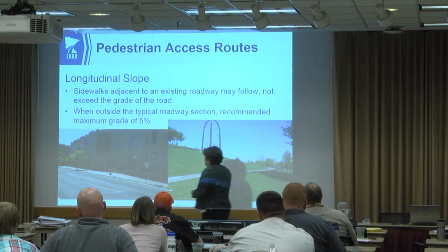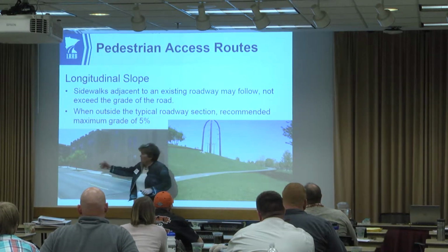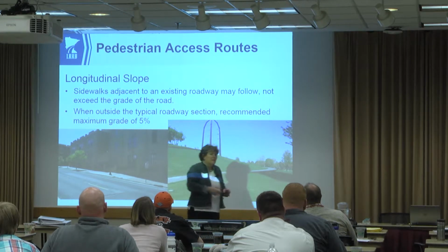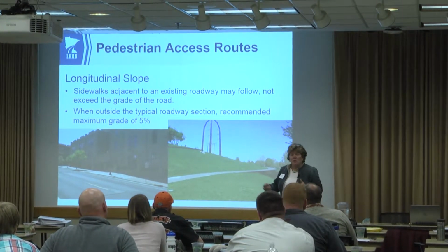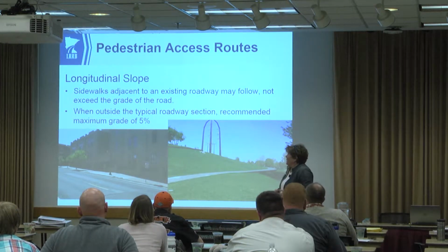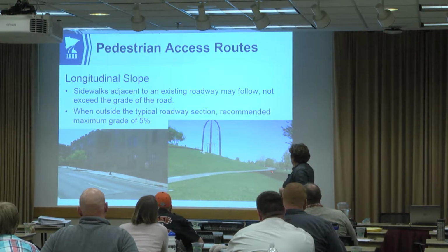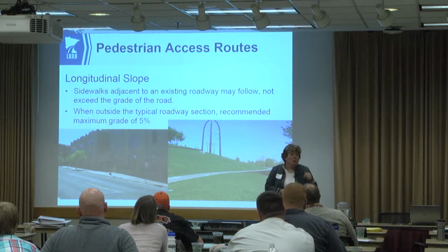Also, as I talk about obstructions, you can kind of see here where the fence post is sticking out, or the column is sticking out a little bit. We want to minimize that, and if you do have obstructions, still need to maintain that 4-foot minimum pedestrian access route. Here we have an independent alignment, and you can see there's a little bit of retaining wall and some shoring, probably to accommodate the fact that the longitudinal slope on an independent alignment must be maxed at 5% unless you're going to start putting in landings and handrails.